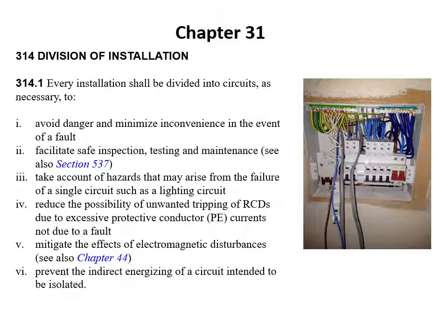If we divide it into separate circuits, upstairs lights, downstairs lights, upstairs sockets, there's always a provision of some form of electricity. It's good practice on the modern split RCD boards to put upstairs lights on the same RCD as downstairs sockets, and vice versa, so that we've got a source of light either by plugging in a table lamp or turning on the light on each floor at all times.